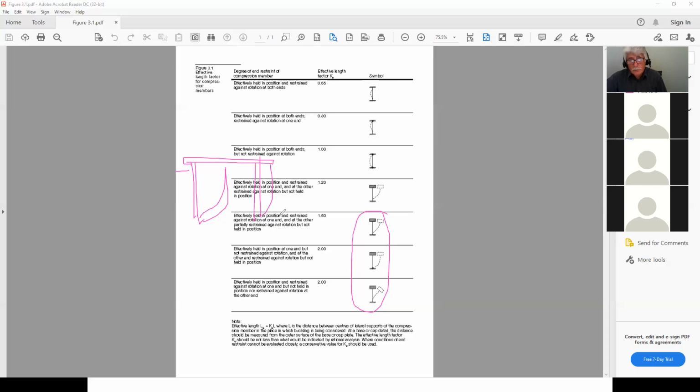If I don't brace this, the columns will be the ones trying to resist the lateral movement. And if you can't create a fixed connection there and there, the whole thing's going to collapse on you. So it's possible, yes.